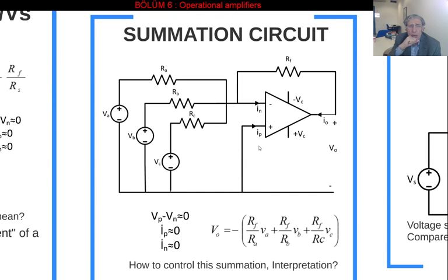That is the summation circuit. In the summation circuit, we've got 3 input voltages here, and this circuit output gives me the summation of these voltages. If you write Kirchhoff current law equations for this node, this is just one node, that means you're going to write 1, 2, 3, 4, 5 current terms here. Anytime you need, you could use the operational amplifier definition relation and then calculate the output in terms of the inputs VA, VB, VC. You end up with this.